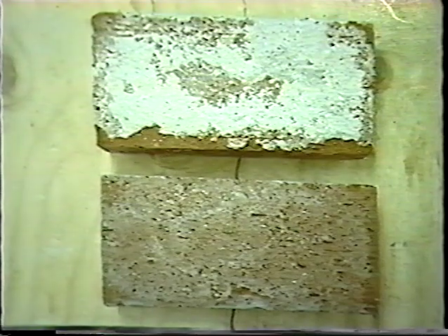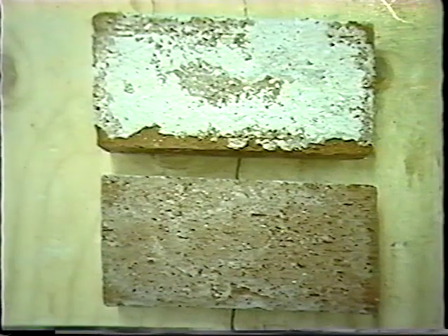Although Portland cement creates bond, too much cement may make the mortar harsh. More cement will cause the mortar to shrink more, which may result in hairline cracks. If too little cement is used, the mortar bond will be poor. The brick on top shows good bond between the brick and mortar. The brick on the bottom shows no bond between the brick and the mortar. Hairline cracks and poor bond allow water to penetrate.